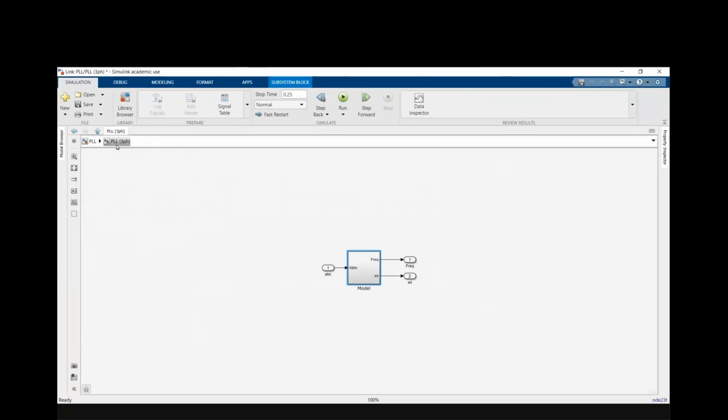This PI may not work at that time. Then what they use is adaptive control. They will modify the KP KI values on their own, which is called an adaptive system, or you can say gain scheduling. With that, they will adjust on their own and give you the corresponding output properly, even after some time. But even an adaptive system has some disadvantages.